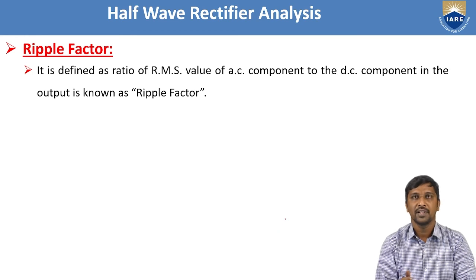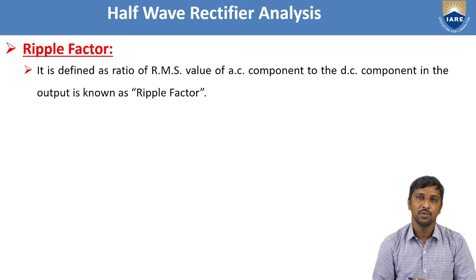Now this is the most important part. Based on the definition, the rectifier is a process of converting the AC signal to a pulsating DC signal. What is the pulsating DC signal? The pulsating DC signal contains a DC output voltage along with AC components. Now we need to identify how many ripples occur in the rectified output.